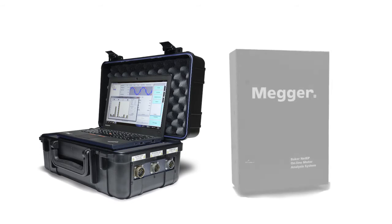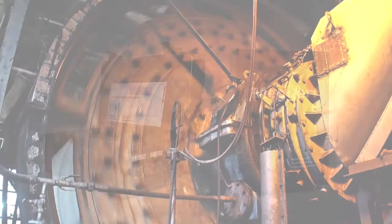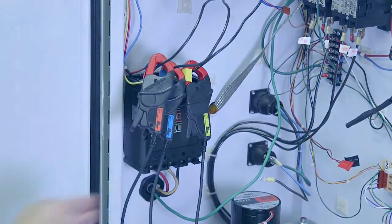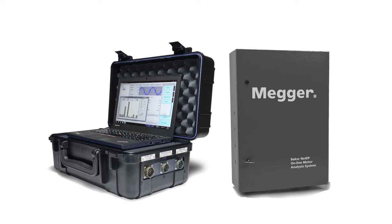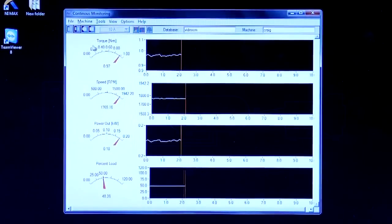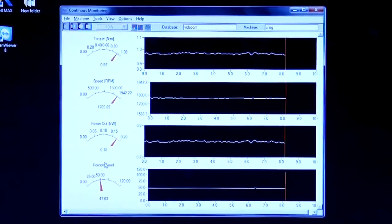Now, let's look at the motor operating point using Baker Dynamic Motor Analyzers. The operating point is measured while the motor or machine is energized and operated. Connections are made to measure the motor voltages and currents. Electric machines are designed for good incoming power conditions. When power conditions deteriorate, excessive currents can flow in the machine, generating excess heat and shortening machine lifetime. The EXP4000 and NET-EP analyze incoming power, including voltage and current levels, distortion, and balance. The motor performance itself is analyzed using motor speed, torque, and load ratings. Motor efficiency is also presented.